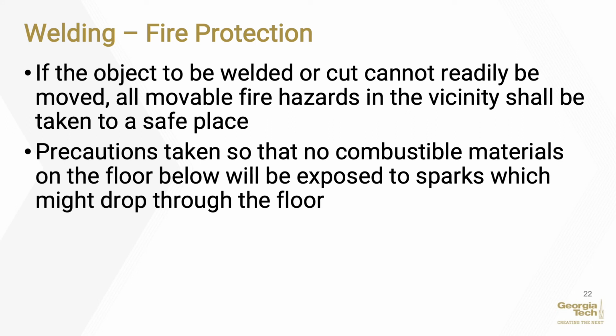It is important for the employer to have a hot work program that covers hot work requirements, including permits. Require hot work permits in areas where hazardous materials are stored and cannot be removed, or in areas where flammable atmospheres could exist. All hot work is potentially hazardous. Perform an RA, HA, or JSA to determine where the hazards exist.